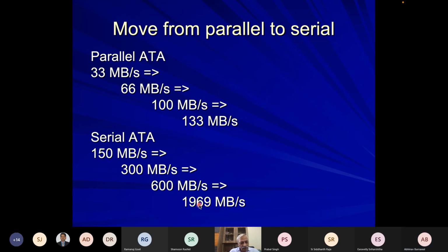Typically, for example, the processor, from these buses, you would be feeding into the memory. So typically, imagine a DMA type of transfer. There is, let's say, data going from memory to the graphic display. On the other hand, data coming from the Ethernet controller to the memory. So these are happening. You have set up DMA, and multiple such transfers may be going on.